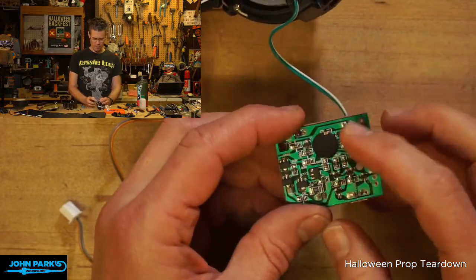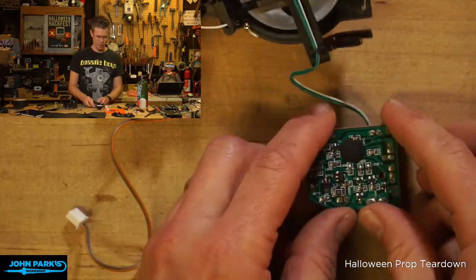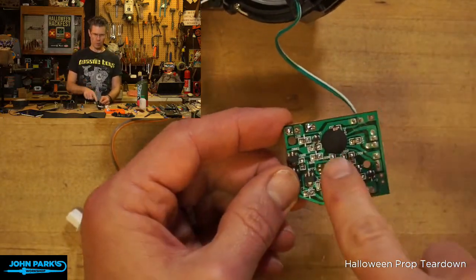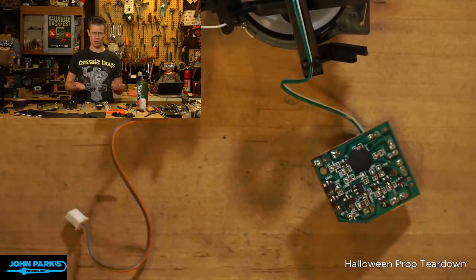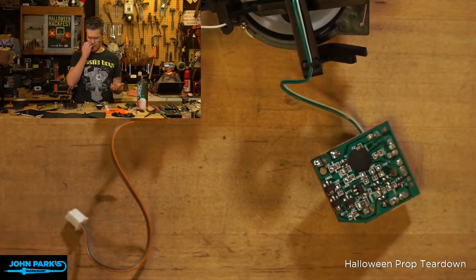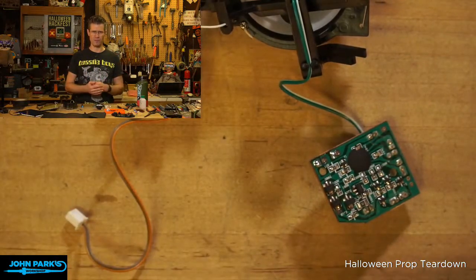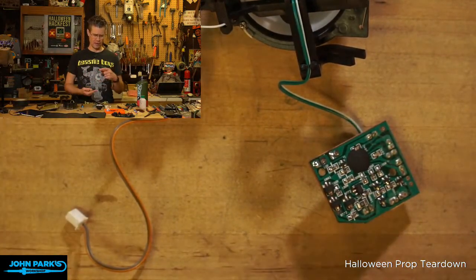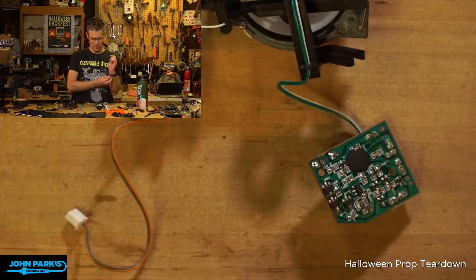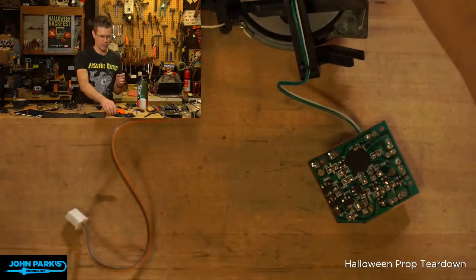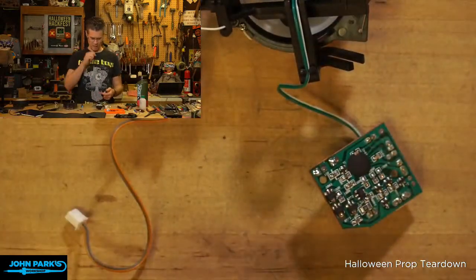You're not going to be able to, I know a lot of people ask, oh, I'd like to put my own phrases on here. If you're going to try something like that, you're, again, essentially going to ignore the entire microcontroller board at that point and instead use something like the Cricket or maybe the Prop Maker Feather Wing, where you could do CircuitPython MP3 playback, and it has a little amplifier built in, so you could run to this existing speaker that is in here. So you can transplant essentially the brain and use the mechanism and the motors yourself.